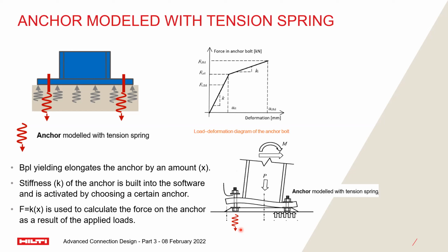Again, here you have to be really specific on this coefficient especially. Basically, every anchor has a different stiffness factor. This is really important, by the way, for every kind of calculation like this. Every anchor has its own stiffness value. You might be familiar with a couple of our anchors. Even within the same anchor family, whatever we name it, a different size of an anchor can have a bit of a different stiffness value. I don't remember how to comprehend it, but just know that every anchor has a different stiffness value. So that's why these are really tough calculations to do by hand. That's what I was trying to say at the end.